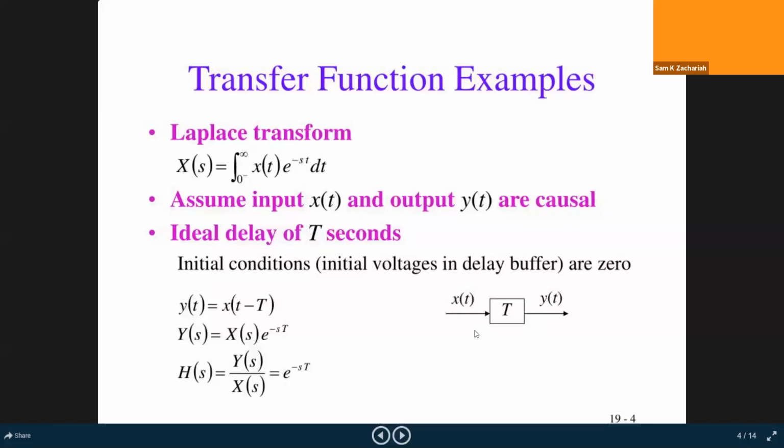Sorry, that is a static system. A dynamical system is one where the current output depends on previous inputs. Under that category, the simplest element is a delay element T. If capital T equals 0, then the instantaneous output depends on instantaneous input. Otherwise, this is the simplest thing.